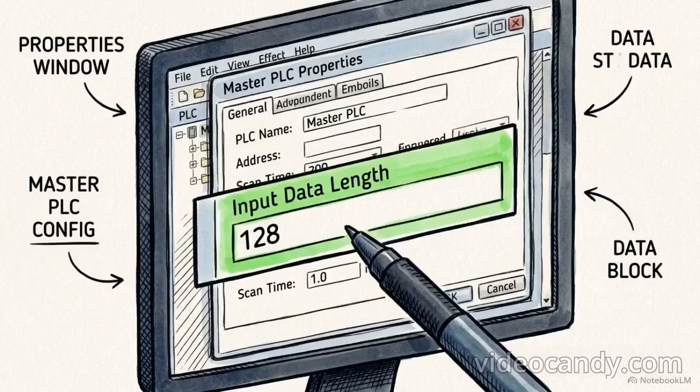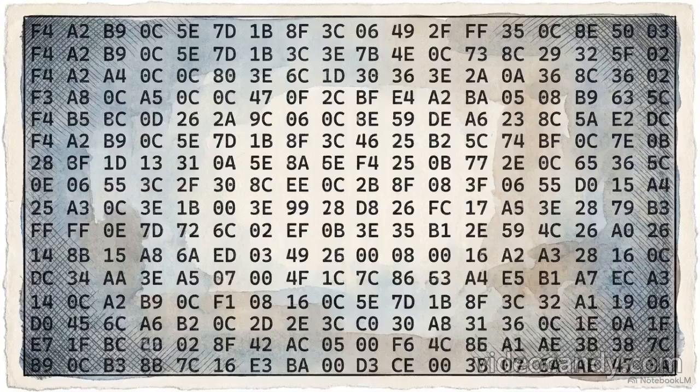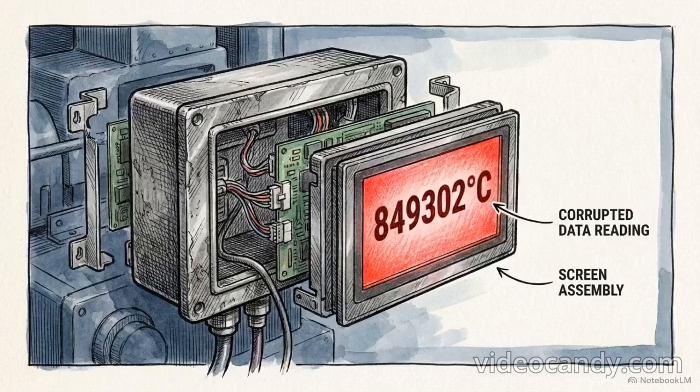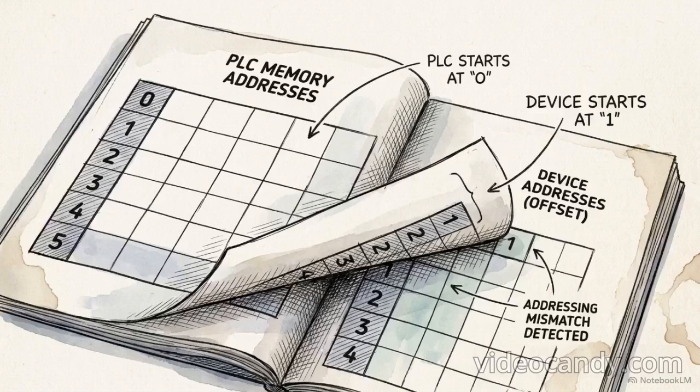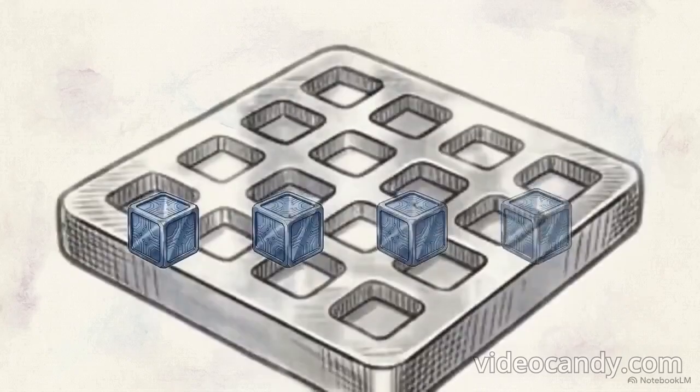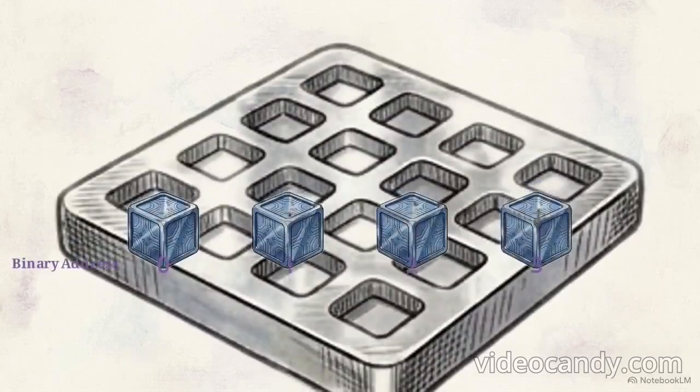the payload. The master PLC knows exactly how many bytes of data to expect from the remote station, but it has zero context for what those bytes mean, or how they should be interpreted. If you treat a GSD file as a complete, start-to-finish integration tool, you risk the systematic misinterpretation of complex analog data. The first trap when cross-vendor devices share memory blocks is the misalignment of register indexes.